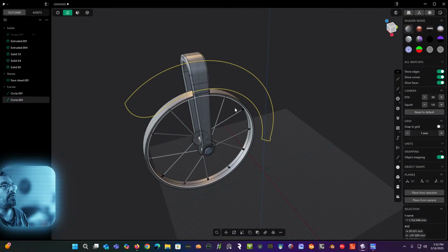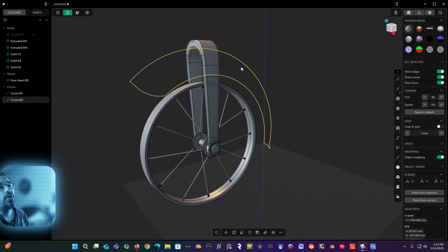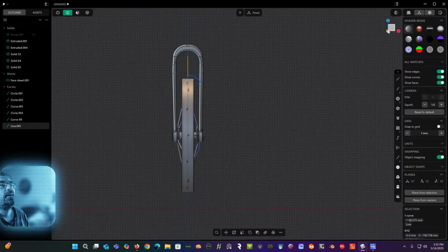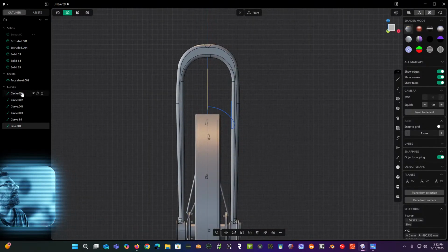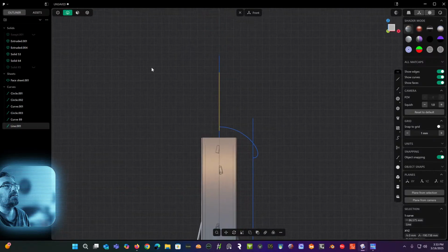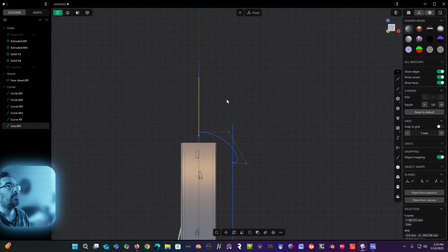I don't know if it's going to curve properly in the middle without guide curves. And you know what? I shouldn't have put those together because those are going to be my guide curves. So from the front here, or from here, I can make a line just to act as a guide curve. And then I can go back here and adjust it. Let's hide our little handlebar thingy. But I can adjust the points of this now.